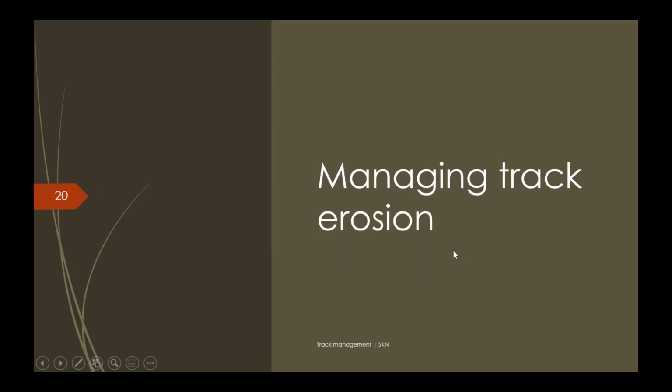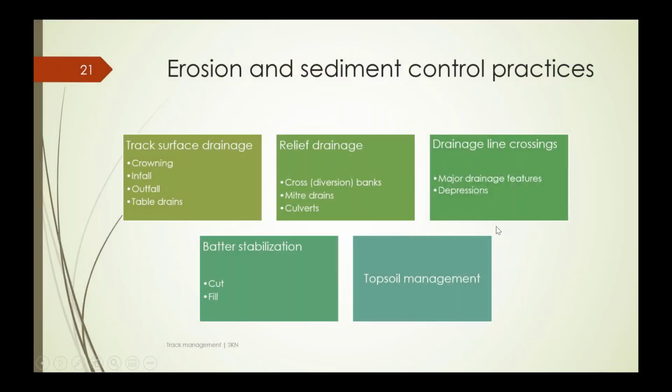Okay, so the various tools that you have at your hand to manage track erosion really come down to a range of measures, but in a lot of ways it boils down to drainage, track drainage being the basis of a lot of these measures.